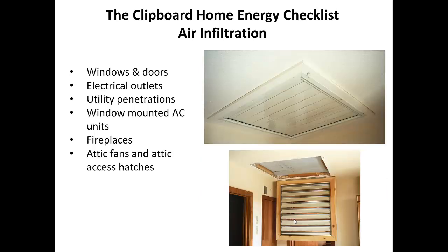Attic fans and attic access hatches. This is in a home that I built. We had an attic fan up there. I like to use attic fans, but boy, in the wintertime, they lose lots of heat that comes down through it. So what I did was create a styrofoam cork, if you will.